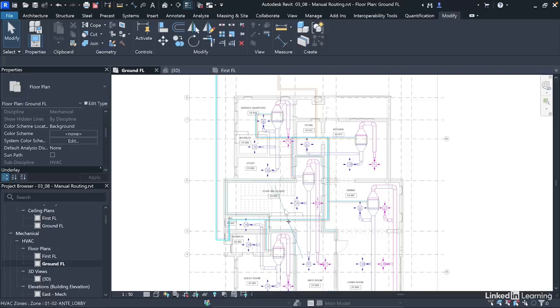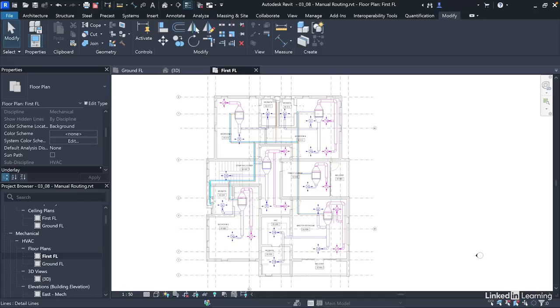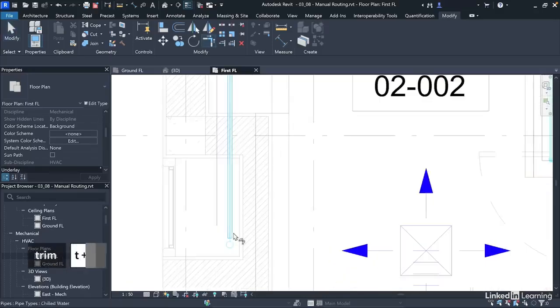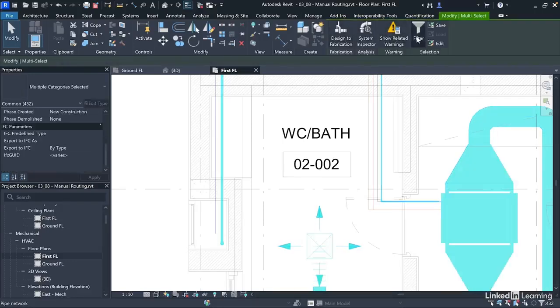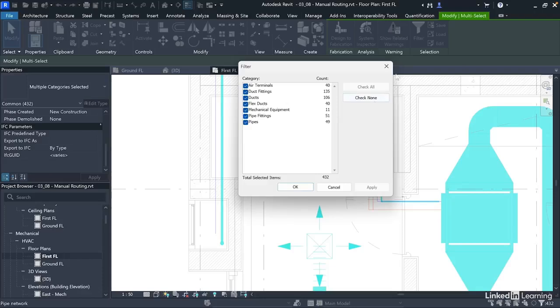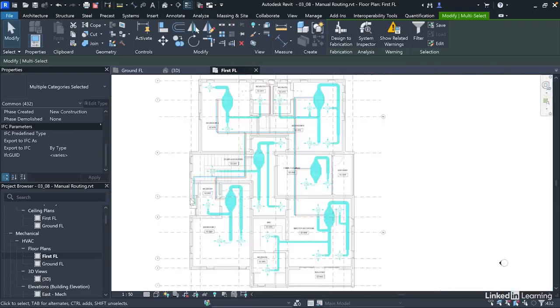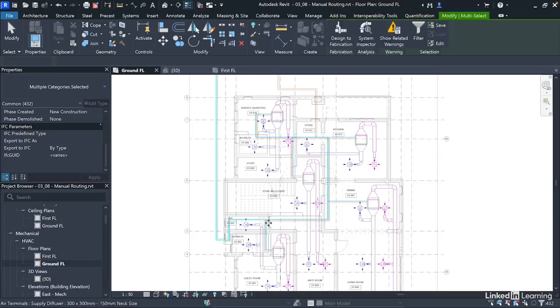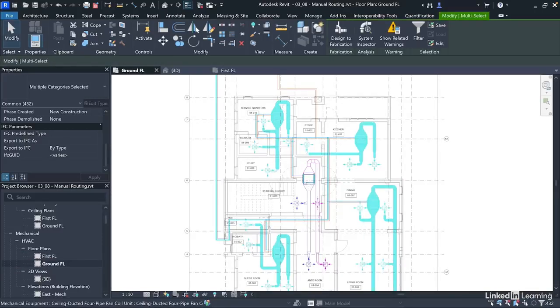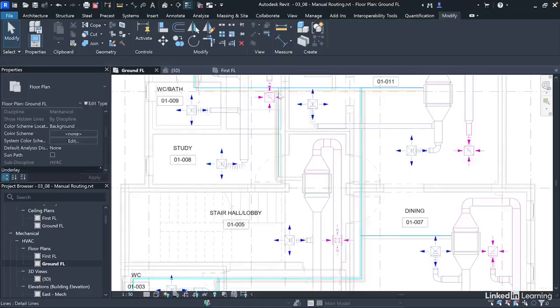Okay, the reason is because we've not connected into the ground. So we come here, can use the trim command to trim this and this. Now everything has joined. So now if I use the tab key to select everything this way, then if I filter this, I should have 11. So one is not yet connected. So these 6 are connected. On the ground, this one is not yet connected. So I need to make sure that everything is properly connected.